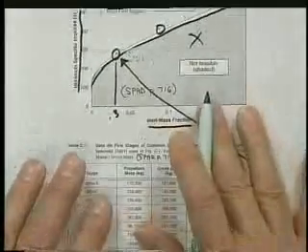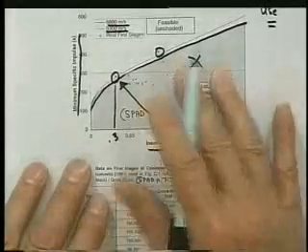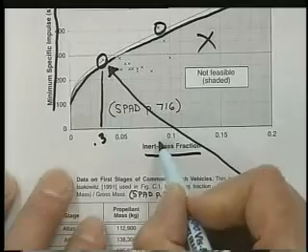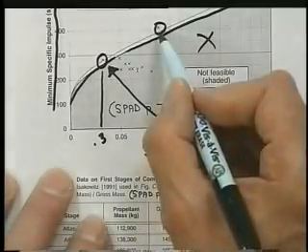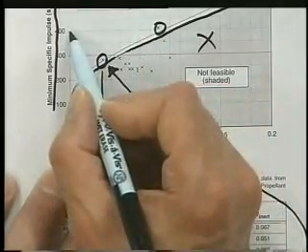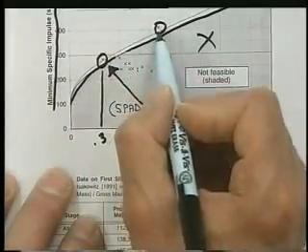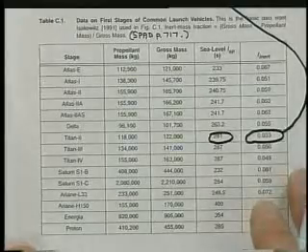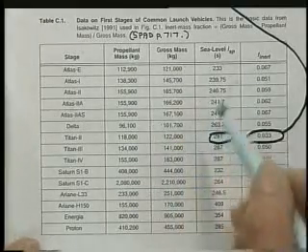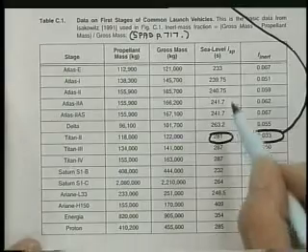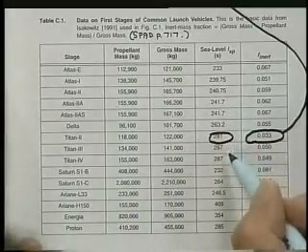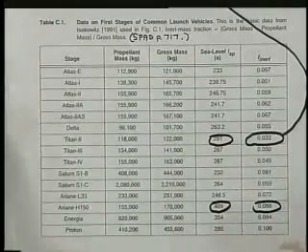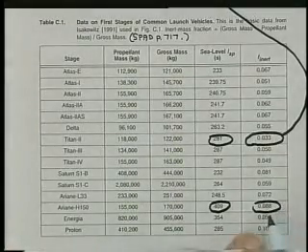We have another case where a single stage can get into orbit, and that's up here. It's got a mass fraction of around 0.09, maybe a little less, and then an ISP greater than 400. So if we look at that case of an ISP of 400 on these actual values, the value of 400 is right here, 409, and here is just slightly under 0.09 or 9%.